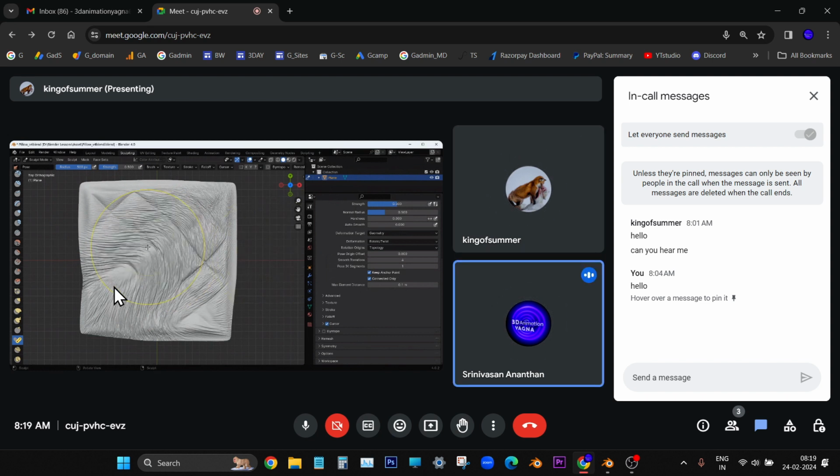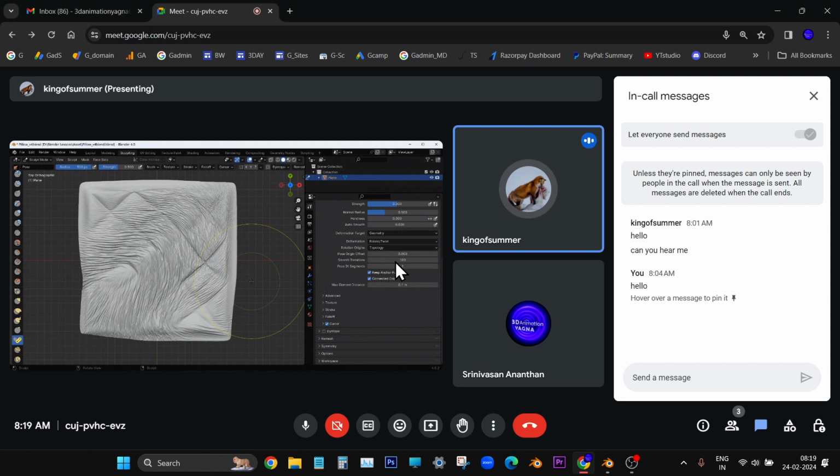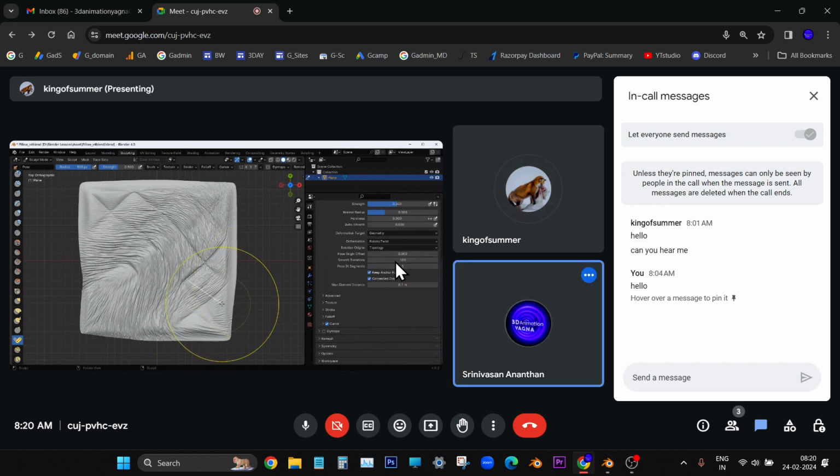One undo. Yeah. Now you are seeing some options in the right side properties panel. In that, make smooth iterations 100. Down. Yeah. Smooth iterations 100. Right. Now, on any corner you keep your cursor, and then slightly turn it.